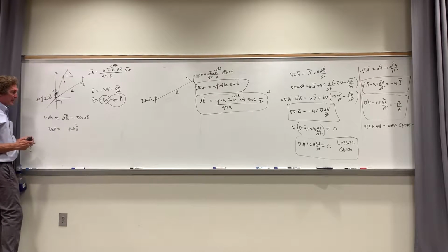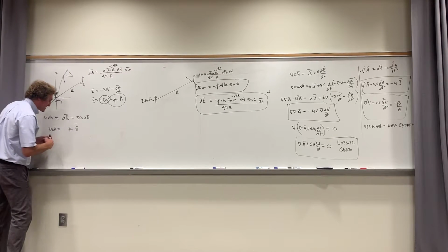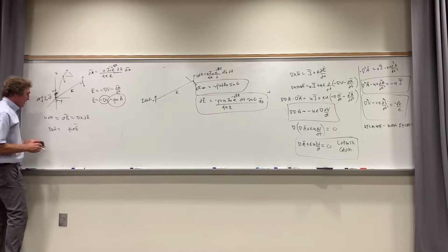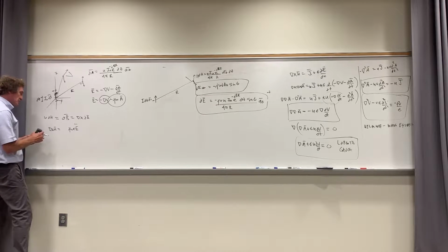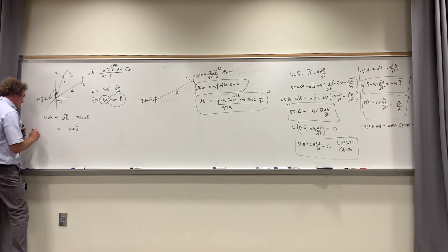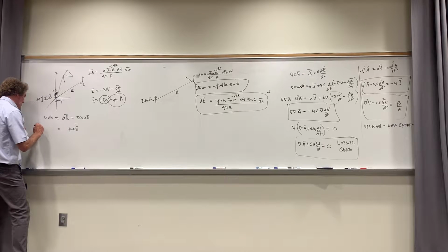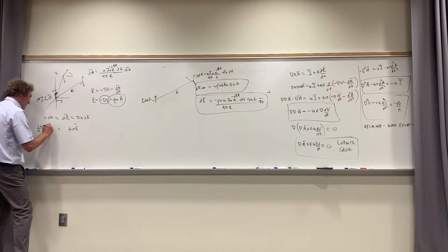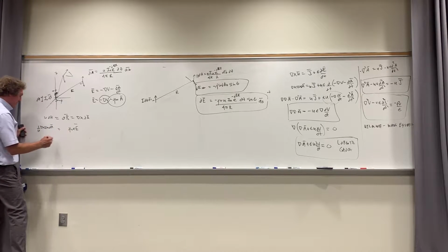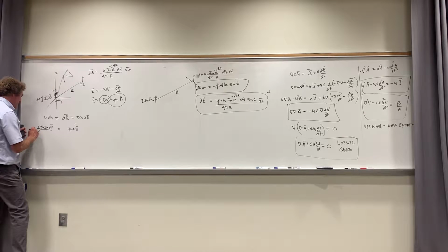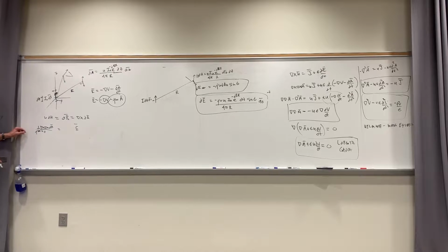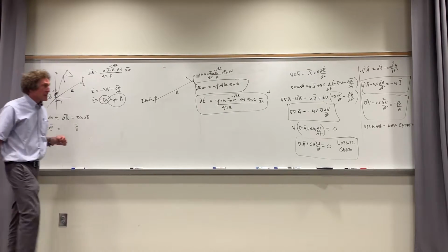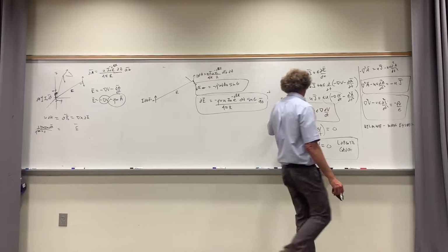So I have j omega epsilon E. Well, I have curl of H, and if it's a differential, then it would be curl of dH, which would be 1 over mu curl of this dA, right here, equal to that. Then you would divide by j omega epsilon, and you would get E, and that curl equation is what is expanded right here.